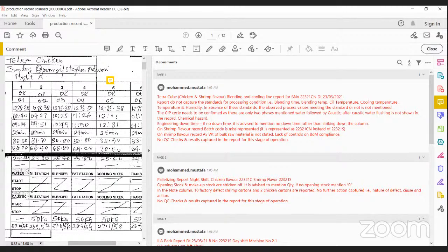I just explained now that the process is automatic. The process starts automatically when the service starts with a rinsing. After the rinsing, then the water flushing before the caustic cycles. After the caustic cycles, then the rinsing, and until the CIP process ends, based on the time set for the concentration of the cleaning of the caustic from the line to be okay. Do you get me now?